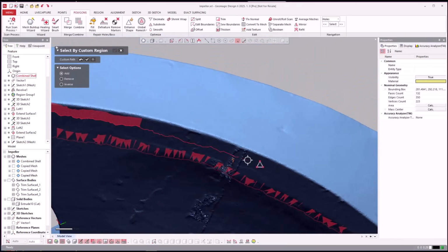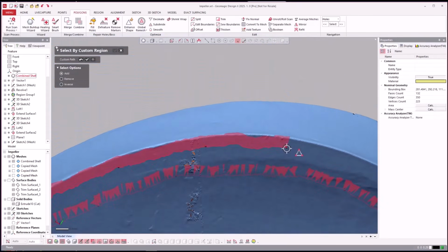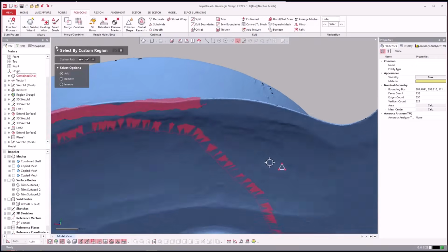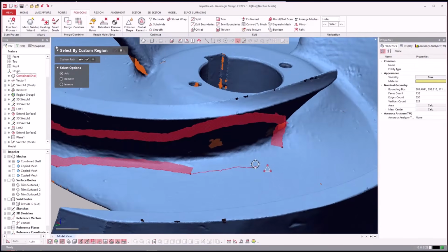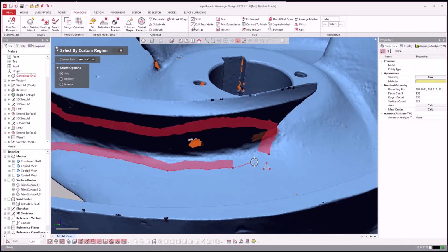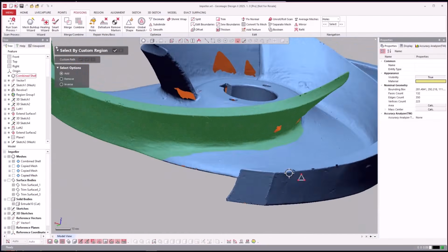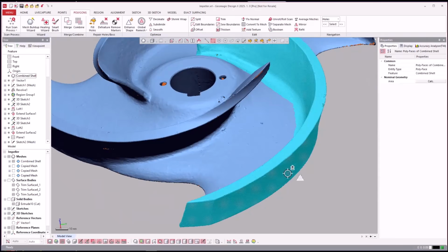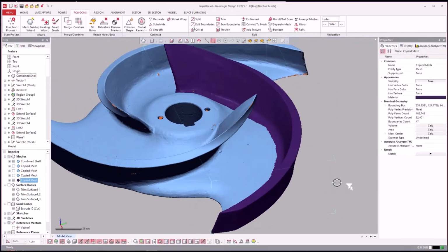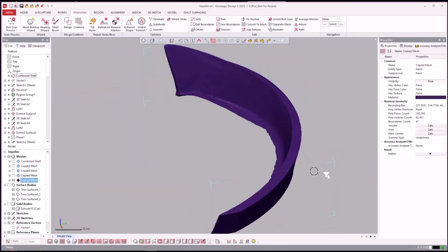Now you can do this another way, right? Like you can go around and select this geometry. You could duplicate the whole mesh and just delete everything else, and then when you double click here, it will close that shape in, and if I accept it, there's my selection, and I can do a Control C, Control V, and I can copy and paste that. So that's all we did.